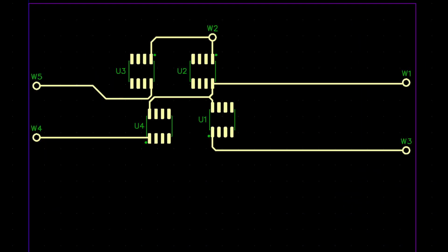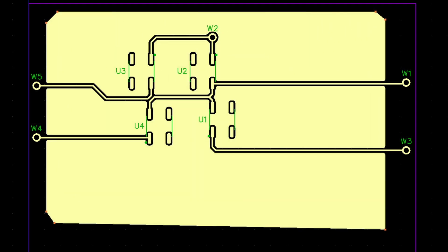When a copper pour, which is associated with a particular signal, power or ground, is poured around a component pin which is of the same signal or power or ground, DipTrace automatically connects that pin to the copper pour or plane. It does this in one of two ways. There can be a direct connection, which means that the pin is assimilated into the copper pour and becomes indistinguishable from the plane. This is not a bad thing when we're talking about the vias used to connect the planes and various layers together, because there's no soldering involved.